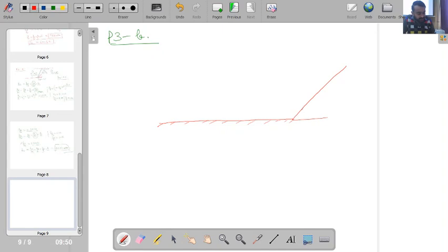Here it is given that I have only a single deflection, and there is formation of an oblique wave. This wave is such that in the upstream I have the same Mach number of 2.8 and the same initial pressure of 1 atm.